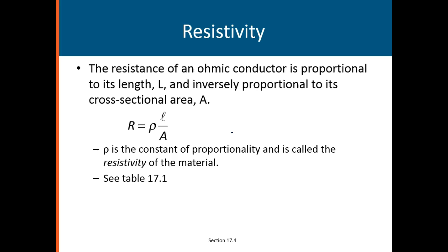Sulfur, even higher, 10 to the 15th. And fused quartz, 75 times 10 to the 16th. Now, I'm not absolutely certain what fused quartz is and what it's used for, but let me just give you some examples of something that's pretty close to it. Have you ever seen on power poles those ceramic-looking devices that hold the wires off the wood? That is probably, if it's not fused quartz, something very similar. Very high resistivity, so you don't have any conduction through it.